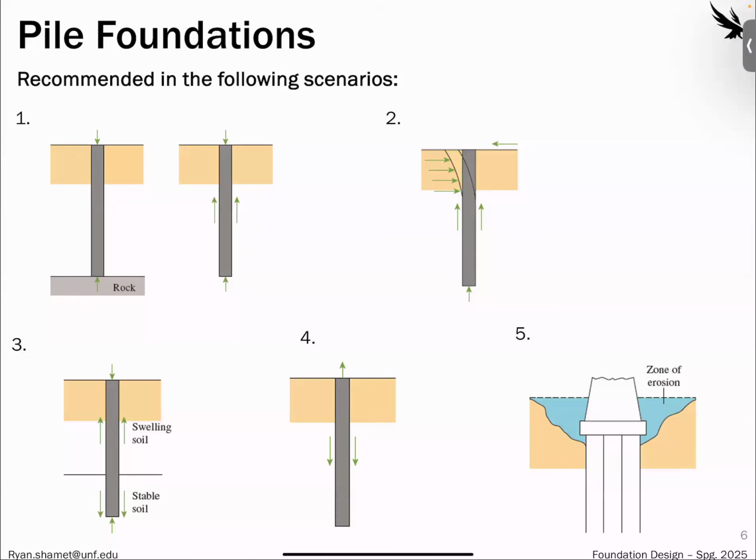So some of the times when you might recommend pile foundations, aside from the bearing capacity and the settlement, is if you have weak ground conditions. Like in the cartoon we showed before, something like organics or very loose or fat clay at the surface. It might be worth removing it, it might not be. Each case is worth the investigation.